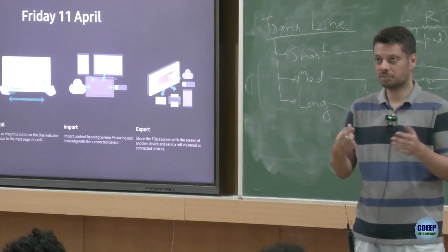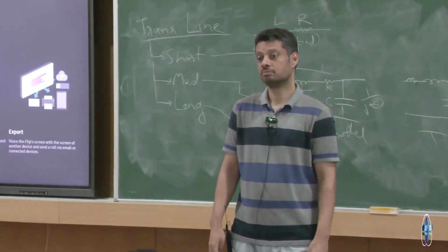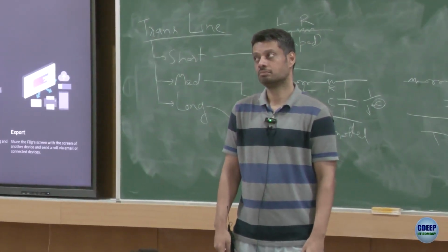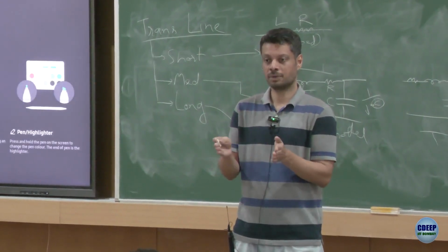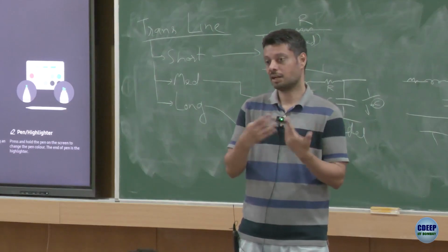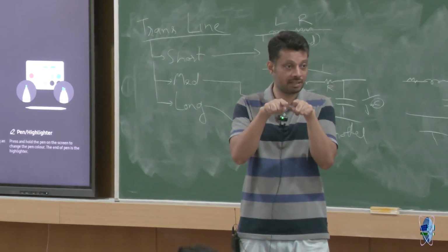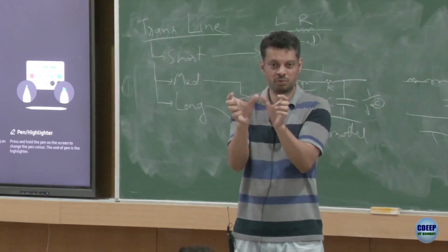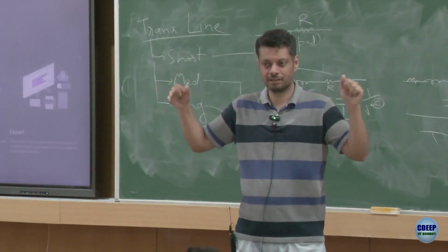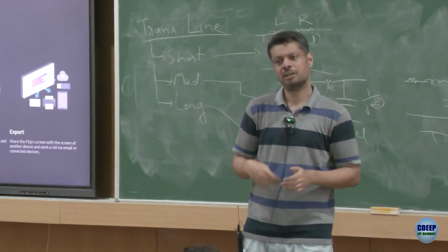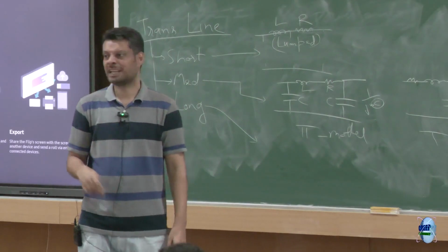Maybe she's saying that you have to dig it, you have to put it inside. No, not that. If you space the wires and the lines, because there's a lot of current, you want to avoid it. Or do you mean that you have a lot of voltage between the two cables? In distribution you have 11 kV, in transmission you may be doing 400 kV. So between the two conductors, you have to have large insulation. You would have to use very, very thick insulating material between the two. So the cables may become just too big, very expensive, right? So there may be some economical factor coming into the picture. But any other reason?